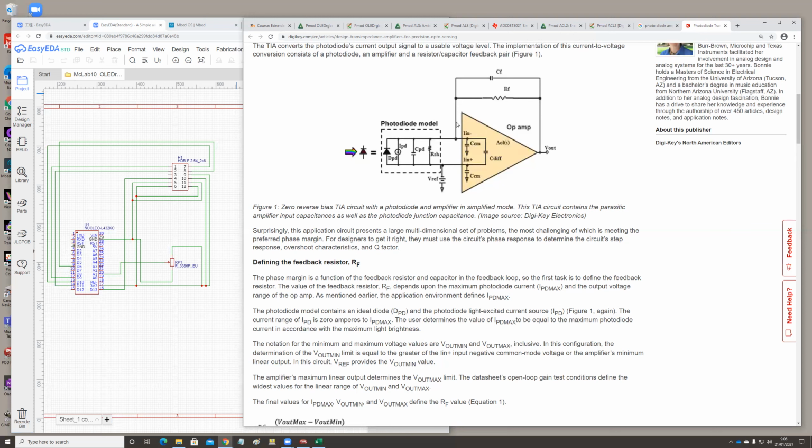When you get some microamperes of current in here, and you put 100 kilo ohm of resistor in here, you get the voltage in the output. So when you get the current in here, you actually get the voltage in the output.